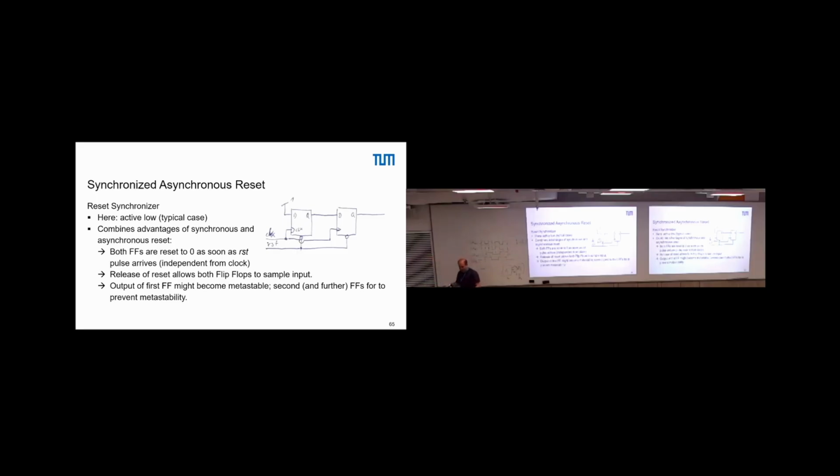And probably I just directly draw this onto this visualizer. So I start with the second flip-flop. We have one flip-flop here, D and Q, and then we connect this to this reset. We connect a global reset here, and we connect a clock signal here.